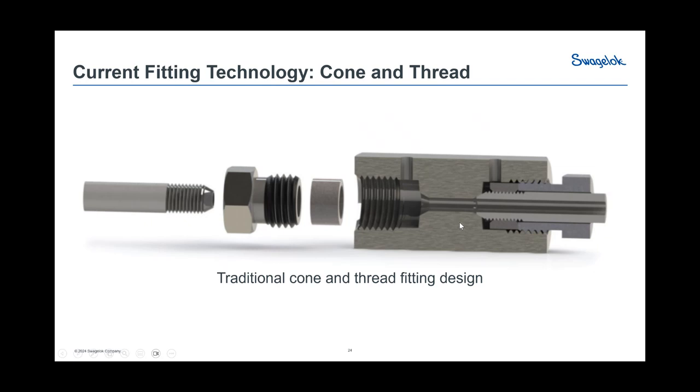The other thing is that the angles are really critical. At Swagelok, we use differential angles. Our cones, we specify 59 degrees and 60 degrees on the taper. So they're very, very close. So there may actually be some areas that can burnish slightly to give us a longer seal area.